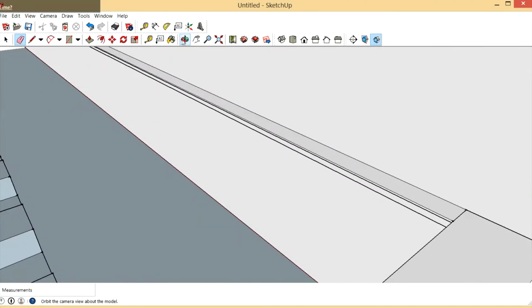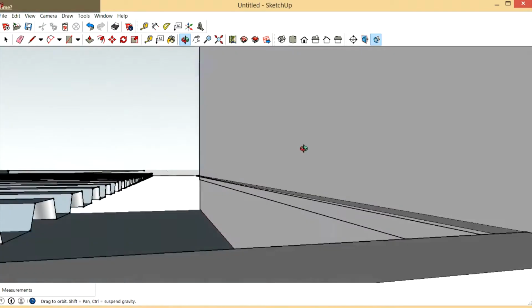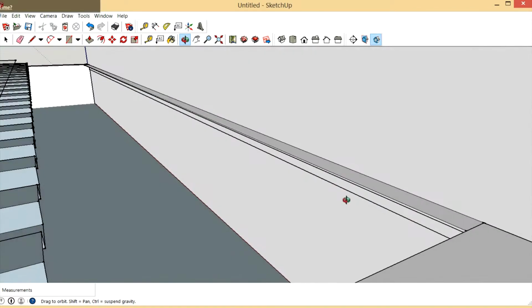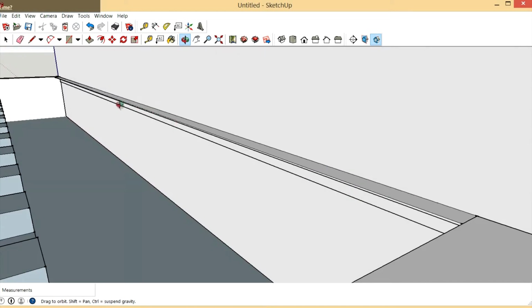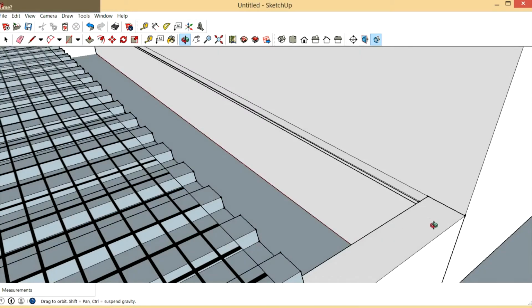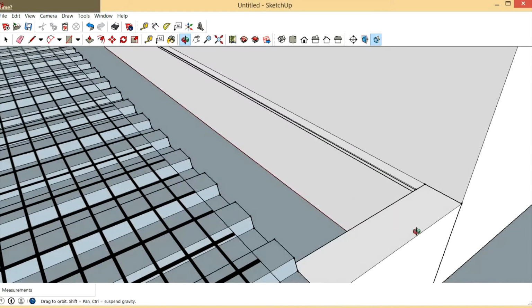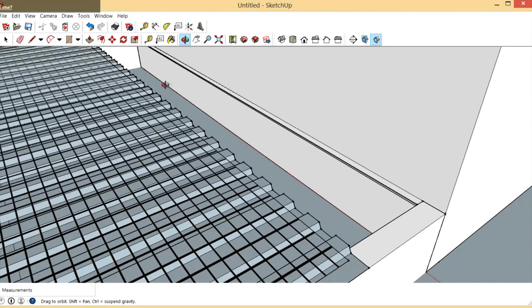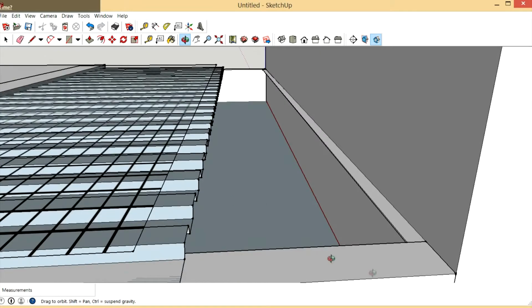And you might want to run lag bolts in that every 12 inches or something, depending on what your structure is there. Because the only bad part about this is that it is now going to be supporting this, unless you decide to run the concrete block wall along there too, which is an option. And again, you may decide, nah, I'm just going to fill this with gravel. But if you're going to do this, then you'd run your pan